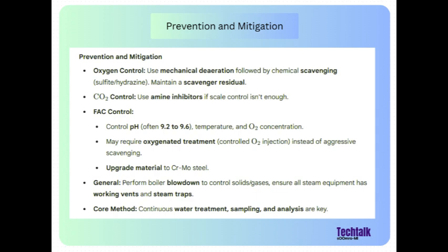And speaking of sweet spots, what's the target pH range again for the feedwater, specifically to minimize FAC? Very tight band. Recommended boiler feedwater, or BFW, pH is 9.2 to 9.6. 9.2 to 9.6. Not much room for error there either. Nope. Drop below 9.2 and FAC rates can really climb.